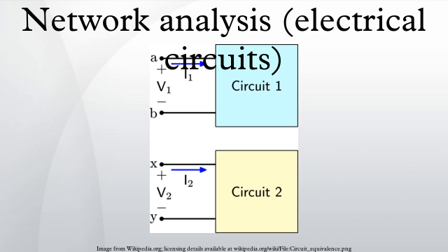The most important parameter for transistors is usually the forward current gain, H21, in the common emitter configuration. This is designated HFE on datasheets. The small signal equivalent circuit in terms of 2-port parameters leads to the concept of dependent generators. That is, the value of a voltage or current generator depends linearly on a voltage or current elsewhere in the circuit. For instance, the Z parameter model leads to dependent voltage generators as shown in this diagram.